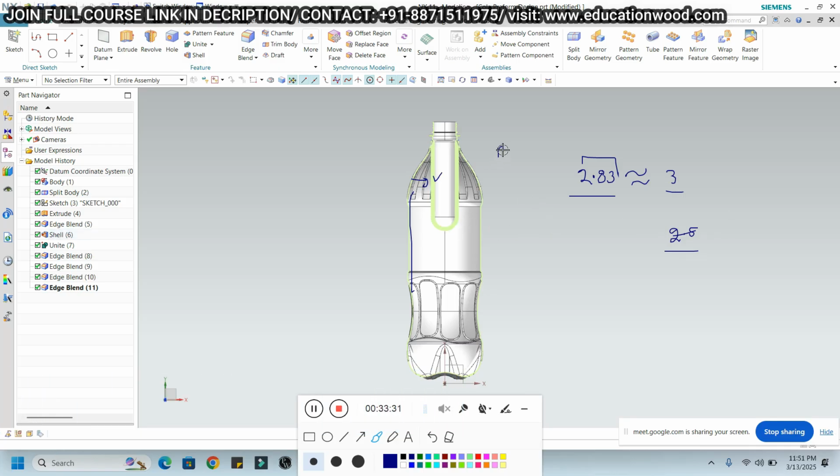If we are working with the Parison, 0.5 is not possible because the wall thickness is very less, and as I told you, we have to work with PP, PC, PET, HDPE or LDPE, PA. So minimum wall thickness for this type of component, we have to take more than 1 mm.